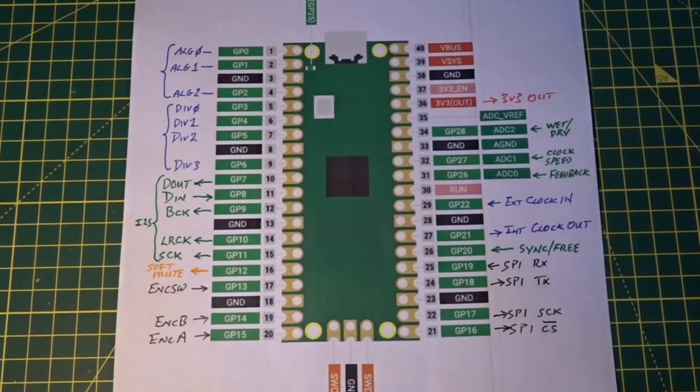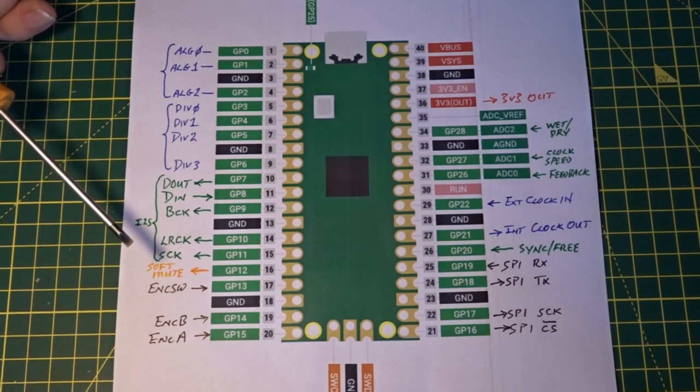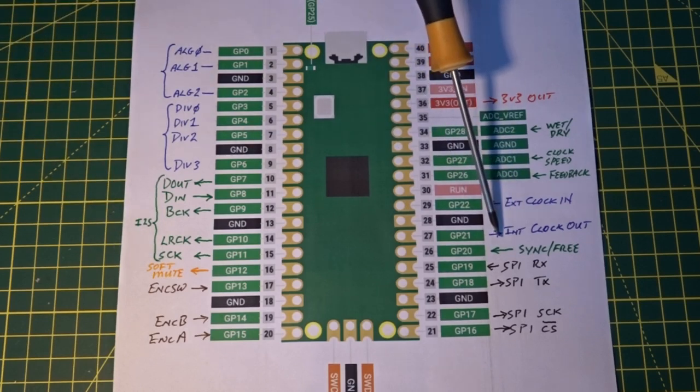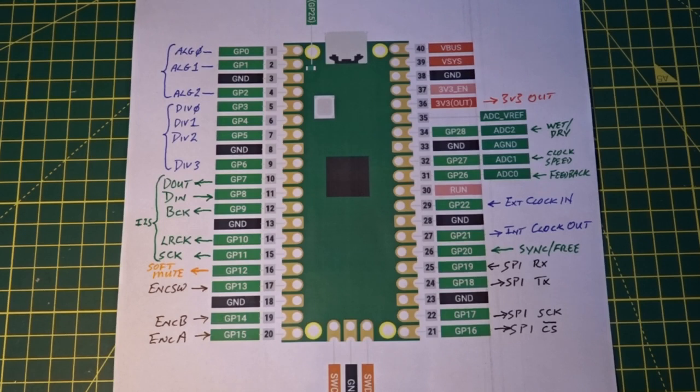For my revision 2 board, one of the main changes I wanted to make was to change the algorithm switch from a 4-way switch to an 8-way switch, and in order to do that, when binary encoded, I needed to change from using 2 GPIO pins to using 3, and I didn't have a spare GPIO pin. So on the revision 1 board I was using a dedicated output pin for the LED, but on the revision 2 board I'm going to drive the LED from the internal clock output from GPIO pin 21, and so that means I can win back an extra pin.